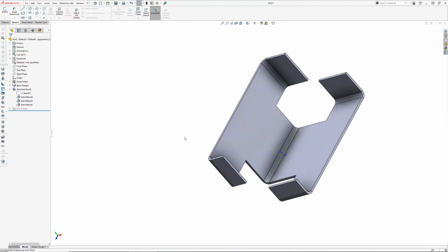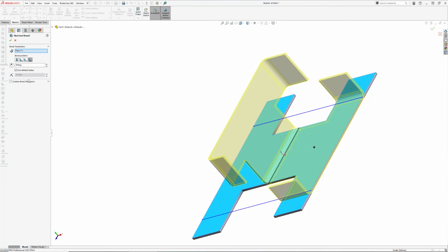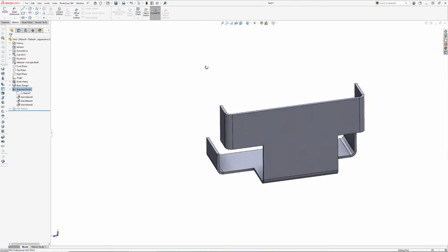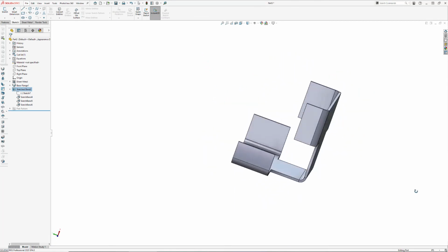So if you want to have another bend that's a different angle, different direction, anything like that, you'll have to create a separate sketch bend feature. Because if we go look at this feature, you'll see there's only one option for angle here and one option for your direction. So not a big deal, but if we wanted to go yet another direction with a bend, we could do that.